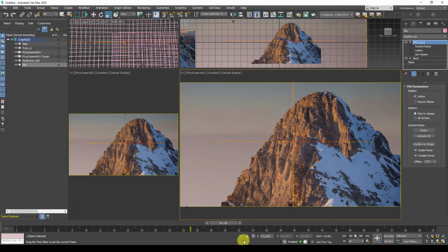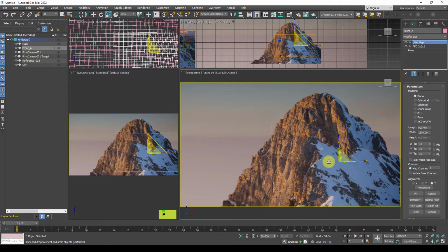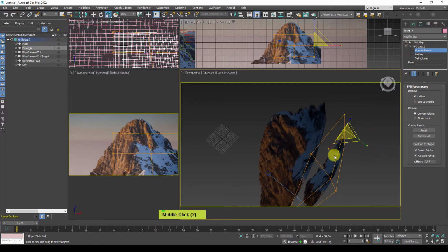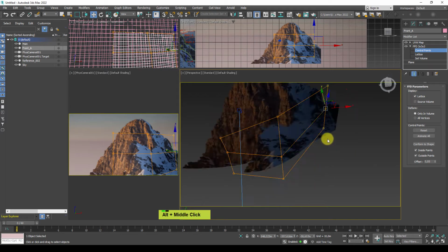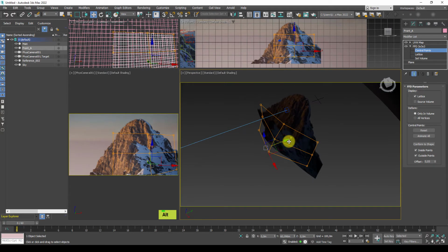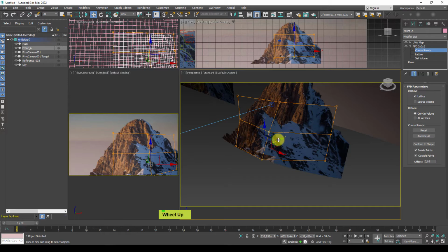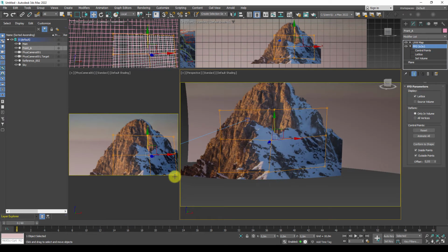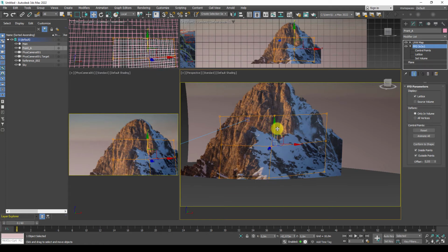What about this mountain? My problem is that the side of this mountain, this side, is a little bit at a bigger distance than here. Because of that, we don't really feel the turn. So what I will do is, in the control points, select these points, switch to move, and move them closer to the original mountain, because I think originally it is closer. Okay. Maybe this should be, yeah, so now I need to lower the whole thing because definitely that is covering. So we want to cover that a little bit better.